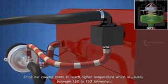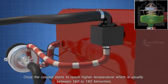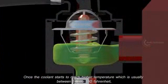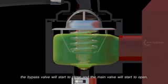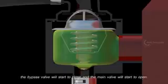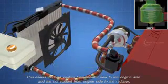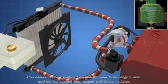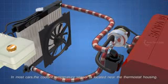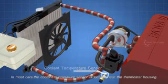Once the coolant reaches a higher temperature, which is usually between 160 to 190 Fahrenheit, the bypass valve will start to close, and the main valve will start to open. This allows the cold coolant from the radiator to flow to the engine side, and the hot coolant from the engine side to flow to the radiator. In most cars, the coolant temperature sensor is located near the thermostat housing.